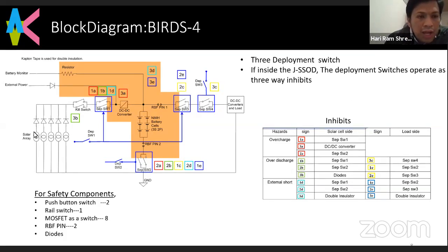And this is the solar cell side. These solar cells are connected in series. Also, we made this solar panel in our clean room, and we designed the panel board similar to the battery construction, which is 3 series to parallel. This one is not available for soldering at KyuTech, so this part we send to a company. So this is that part, and the other parts we develop at KyuTech.